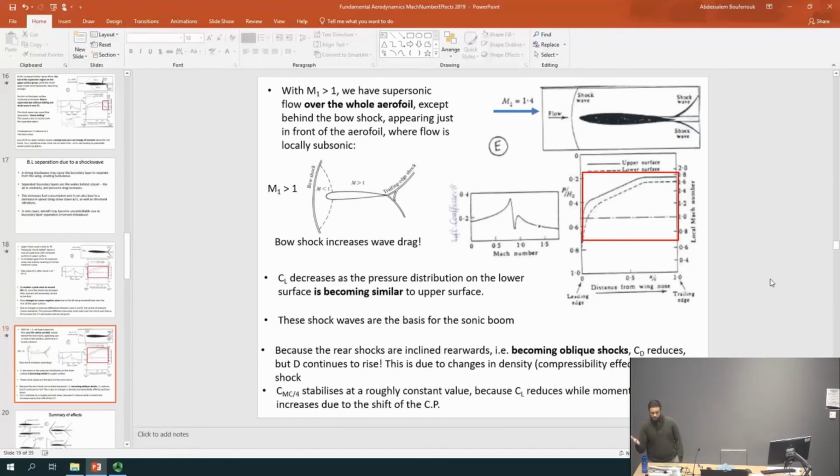They're not universal changes, so please don't take these slides as saying this is the only thing that can happen. They might depend on the shape of your airfoil and the conditions you started with, like angle of attack and so forth. But these are some of the things that can happen. What you should really be looking for is, first of all, how do you identify a shock wave from your runs? And whether that shock wave is a normal shock wave or an oblique shock wave, and whether that shock wave type makes sense in terms of the lift and drag you're looking at, the pitching moment, and so forth. So try to relate what you see in pictures to whether it makes sense in terms of the moments and the forces as well.